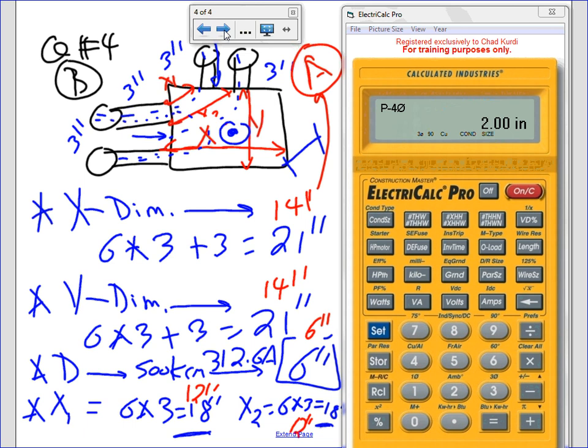The 6, we go by the size of the cable coming from the back. We size it based on the cable. The cables coming from the back are 500 kcmil for both of them. You take the 500 kcmil to Table 312.6(A), under one terminal. What do you get? Yeah, one terminal. Good point, Mr. Oladipo. Okay, can I move to the second one? Number 4, number 5?